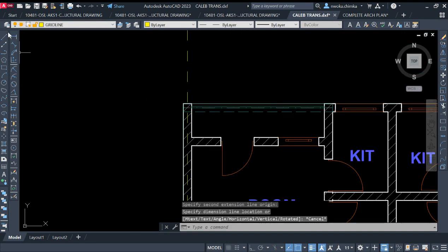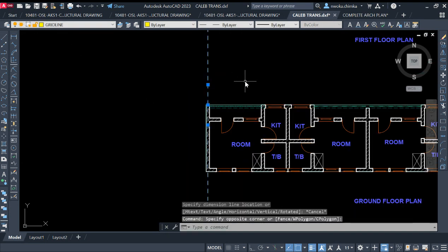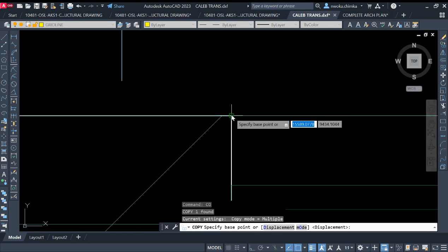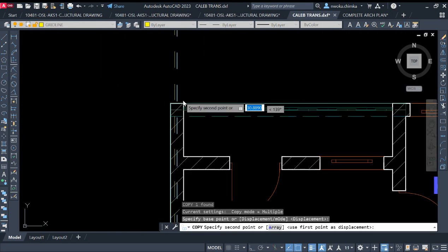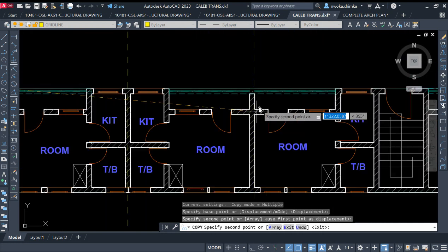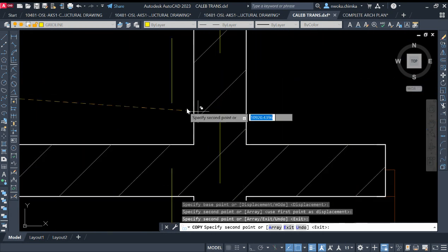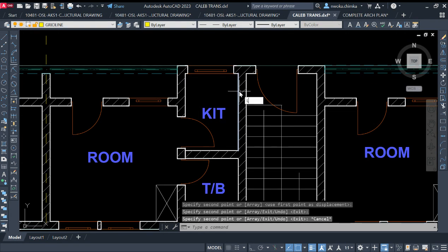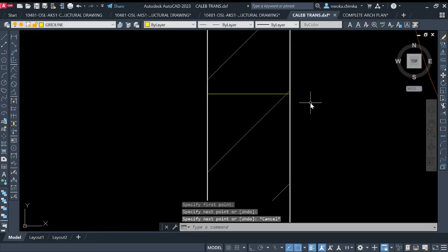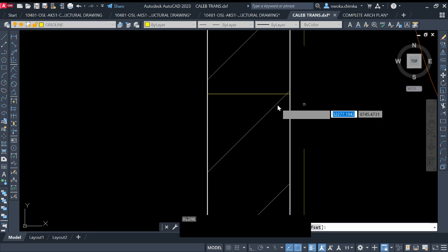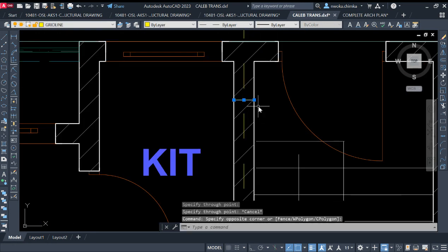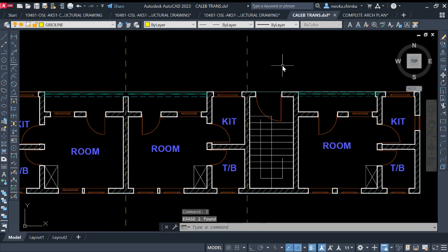So I'll also copy this one and begin to place it at the center of every wall. I'll use these outer points here as reference points, and begin to click at the outer point here and an outer point here. Else, if you don't want to use this method, you can also go this way, by first creating a division line here using L, and then use XL, enter, vertical, enter, and place the vertical line here. Whichever one will be easy for you to do is okay.